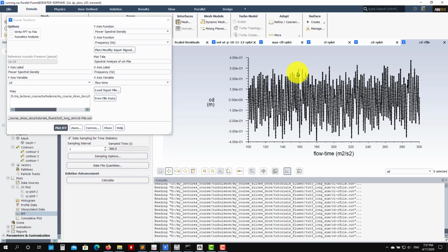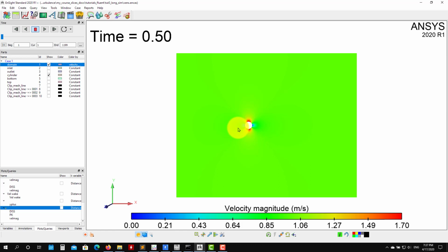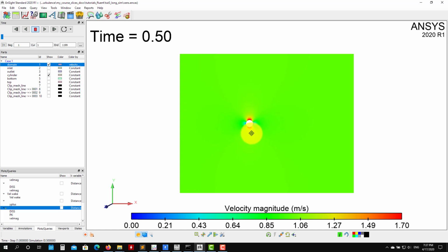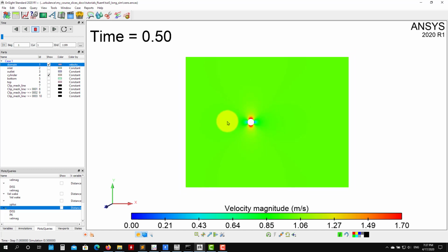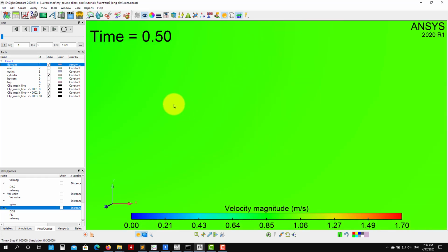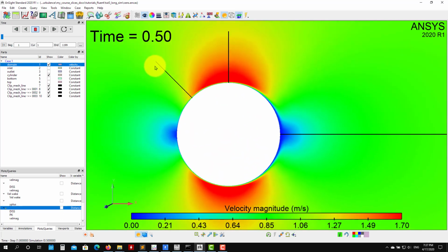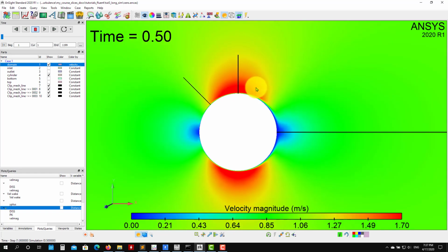And okay, so now I also have a lot of information just to do nice plotting. A lot of people like to do this plotting, so I'm using Tecplot and other software. Doing more advanced stuff is probably a little bit difficult in Fluent. So see here, for instance, I put a few lines. I will do sampling here. I will see, for instance, velocities, vorticity, whatever, and see that I also have these lines here, normal to my surface, where I can do the sampling to plot the boundary layer, the dissipation rate, projection of turbulent kinetic energy. Okay, you can do all the sampling there. So this is more flexible.